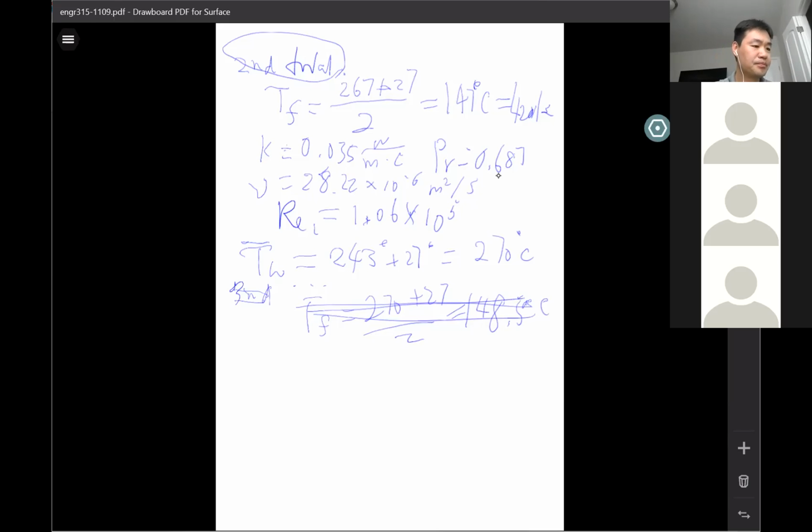Yes, sir. You just interpolated those values from the table. That's what you were saying, the Prandtl number and all that. You don't even need 420. I think they don't have exactly 420, right? If you don't have exactly 420, you interpolate it. They have 400 degrees and 450, so you just interpolate it.